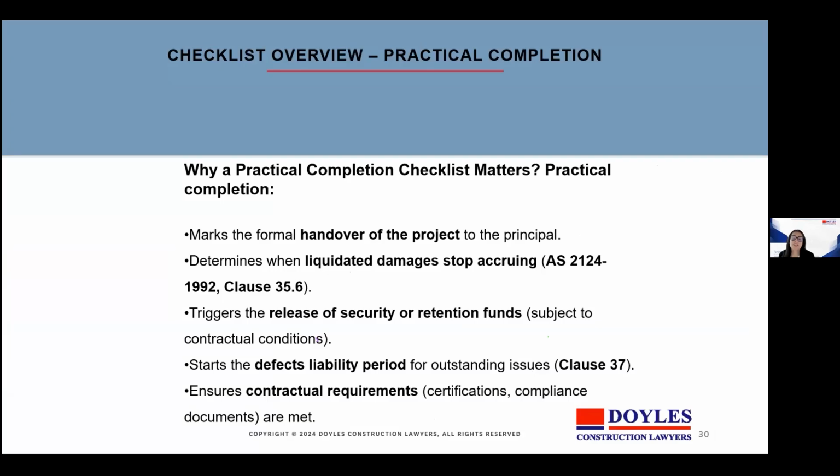It's important to have a checklist for practical completion because it marks the formal handover of the project. It determines when liquidated damages stop accruing and triggers the release of security or retention funds. It also starts the defects liability period and ensures contractual requirements are met. So certification at PC must be accurate and unqualified. Conditional or partial completion creates uncertainty and exposure.